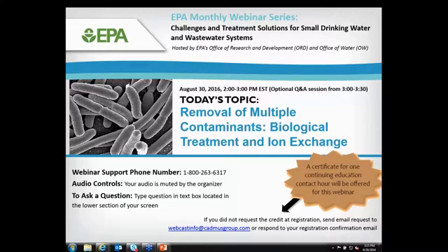Okay, let me take a couple approaches to that question. For a small system, what we see as the advantage would be replacing multiple unit processes. The water plant that I was referring to was using multiple unit processes to remove multiple contaminants. So if you can downsize from two or more processes to a single process, that's what we see as the advantage of combined ion exchange. And why we're looking at the fixed bed as well as the completely mixed is to get a better feeling for which one is more operationally acceptable for small systems.